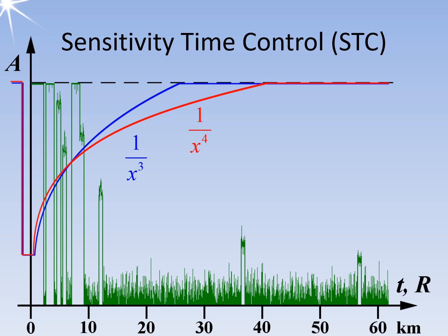Echo signals that arrive at the receiver at the beginning of the receiving time of a pulse period are subject to lower free space attenuation and therefore have a larger amplitude. Echo signals received at the end of a receiving time have a small amplitude because they come from more distant targets. With the STC amplifier, the gain is continuously increased for the receiving time. The amplification factor is therefore time-dependent and, linearly, also distance-dependent.